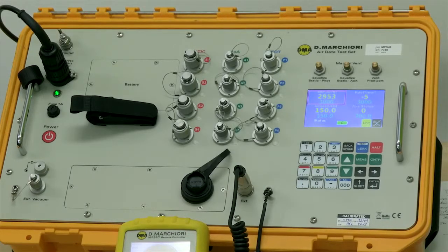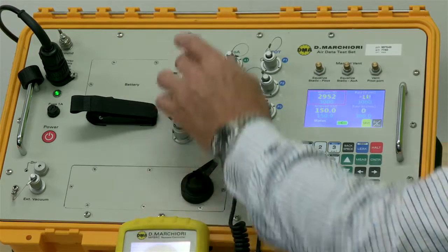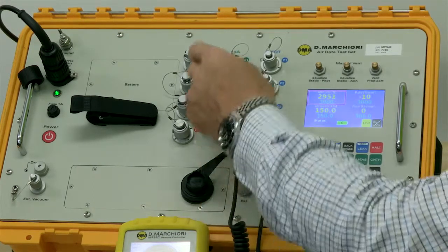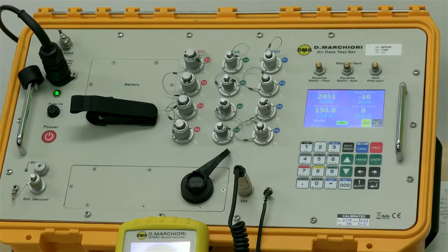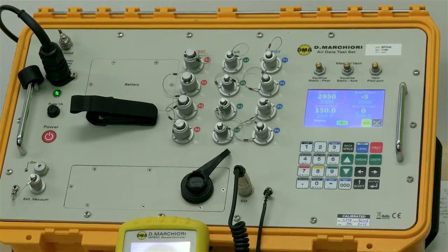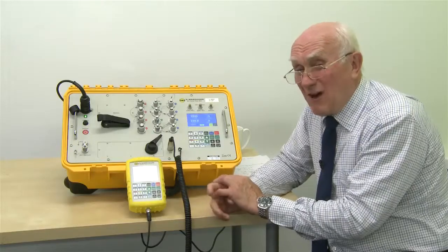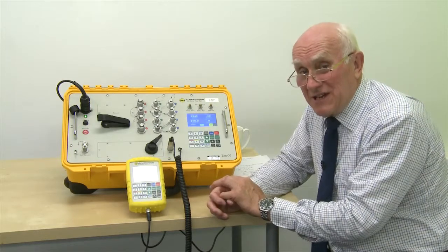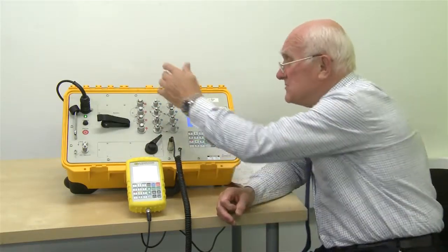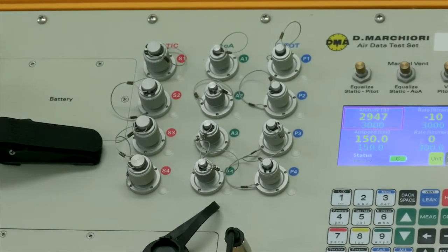Okay, we showed a few moments ago of how you can go into the leak test mode and then see what is happening to the aircraft in terms of what's on the static and the pitot. However, we've already pointed out many people prefer to buy multi-port so that they can cover the individual pneumatic ports you're using, for example, captain, first officer, standby, etc. People like to be able to then examine what is happening across the whole range and indeed find out where the leak is, if there is a leak. And to do that, we have the multiple isolator, and that's what these are. We have the ability to isolate any one of those to find out which is leaking.